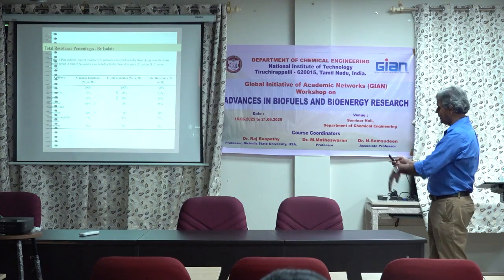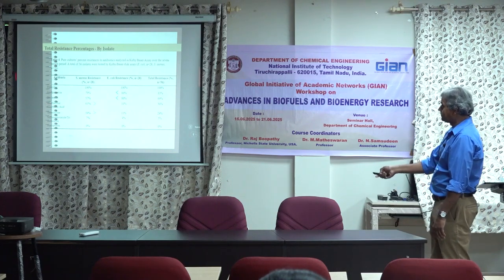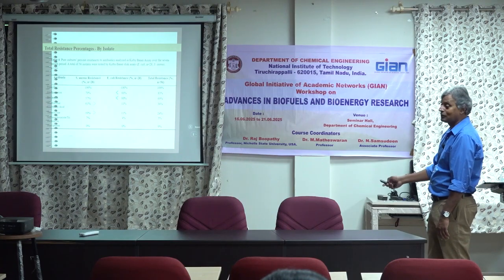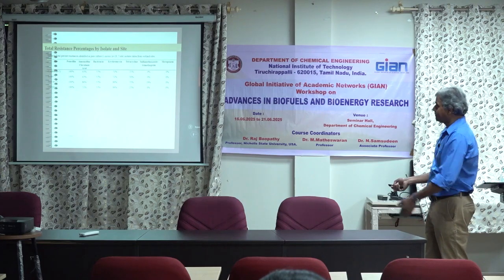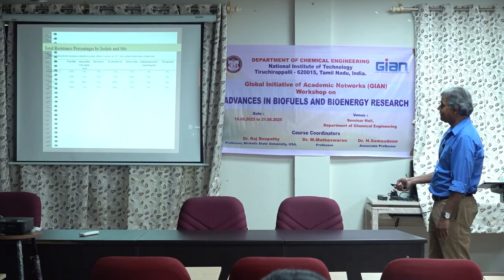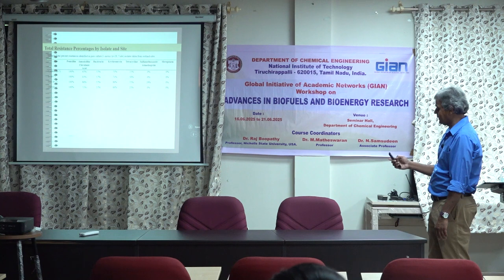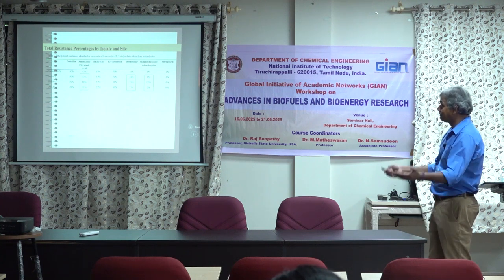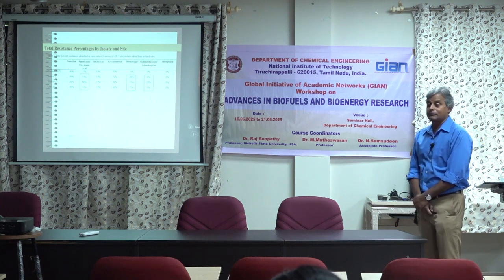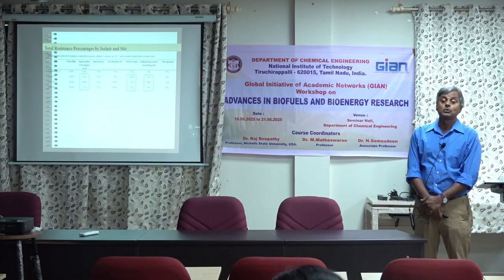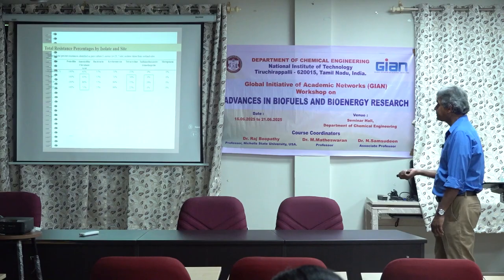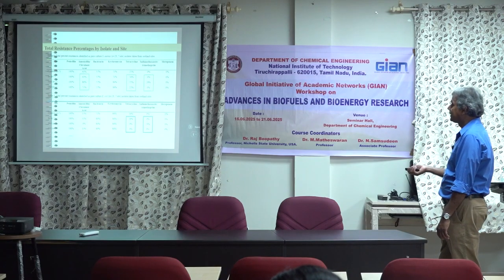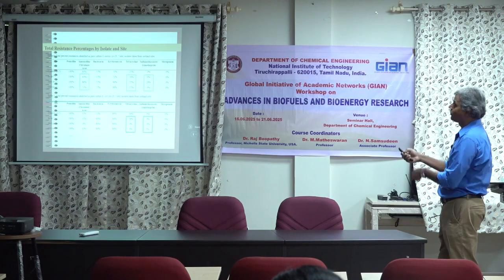and just to list all the antibiotics and all the resistance species-wise, E. coli, Staph aureus, total resistance, as shown here. Okay. Again, the same point in percentage-wise, how many percent of resistance we are seeing here. You can see 50 to 75% of resistant bacteria is removed because of algal action and bacterial action in the wetland. And see the different species, E. coli and Staph aureus. Okay.